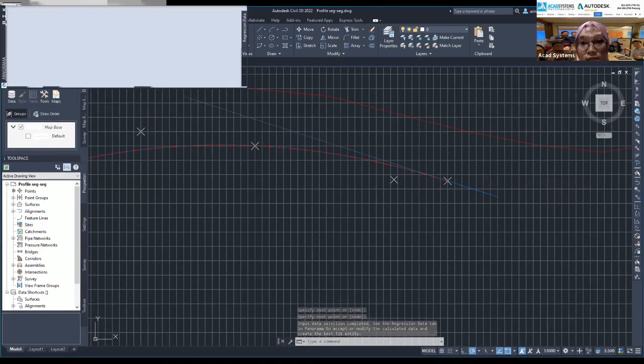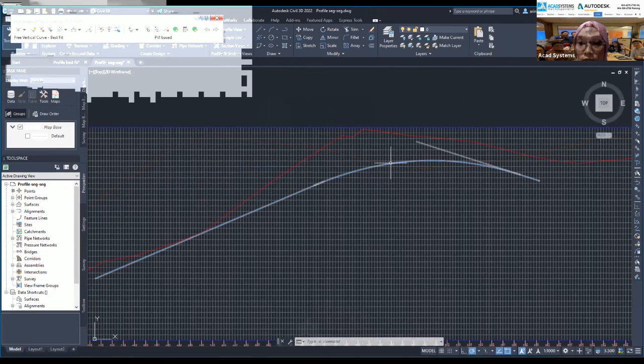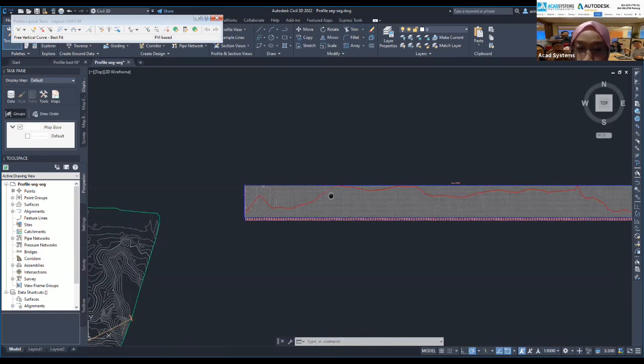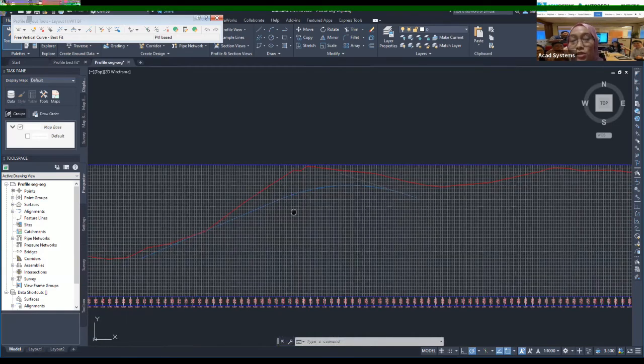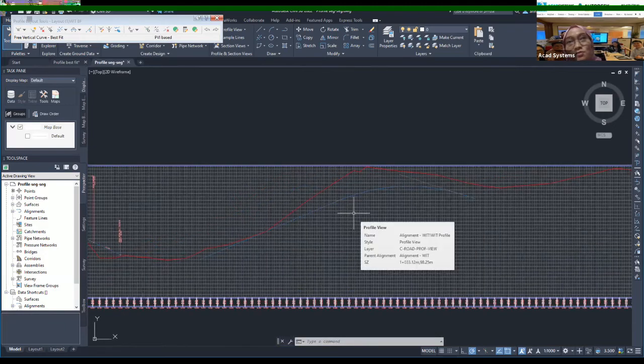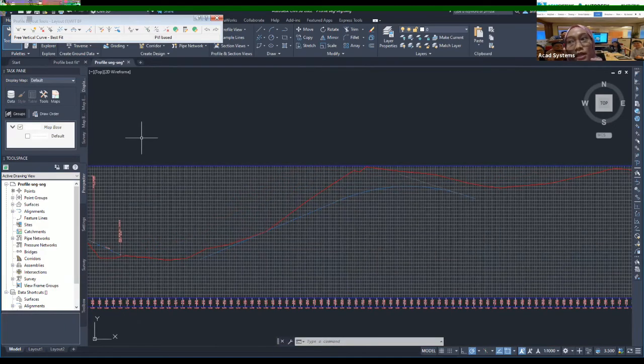All right, so this is the second proposed, second best fit profile, where we create it segment by segment. So basically, this one you create manually. Just now we used the best fit profile tools where it creates automatically for the whole profile.